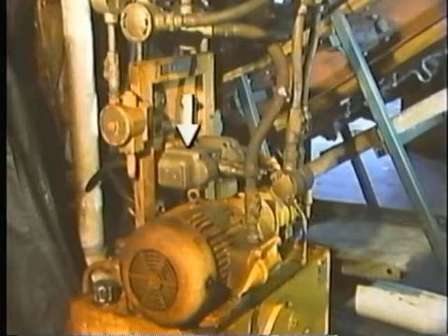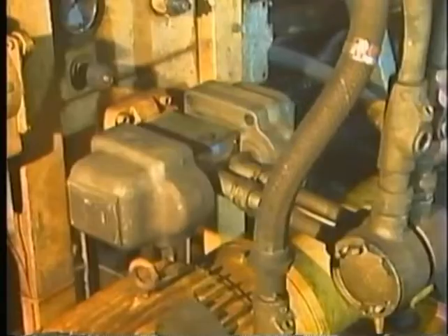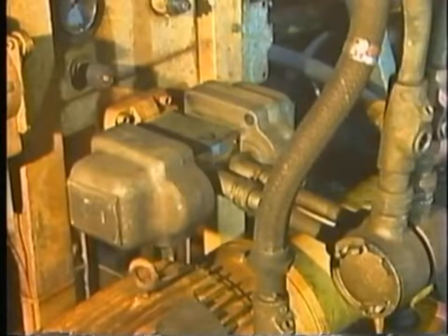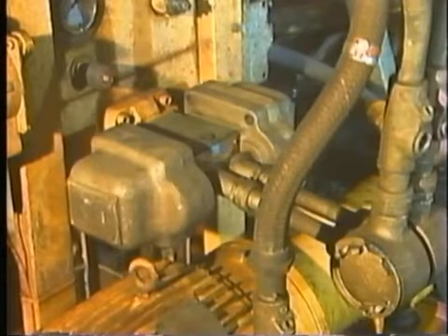Now, that's one way that a directional control valve works. Keep in mind that there are different ways to control fluid direction and different ways that a directional control valve can be operated. The one we just saw was operated manually. However, this is a directional control valve that works automatically. In response to an electrical signal, it routes flow to a hydraulic motor to cause the motor's drive shaft to turn in either a clockwise or counterclockwise direction.